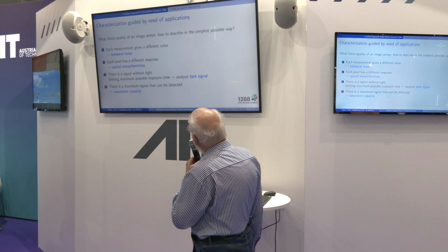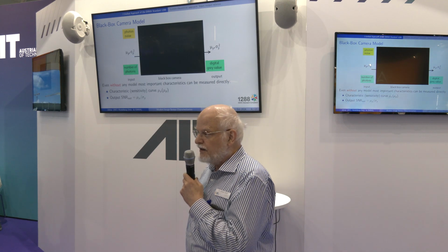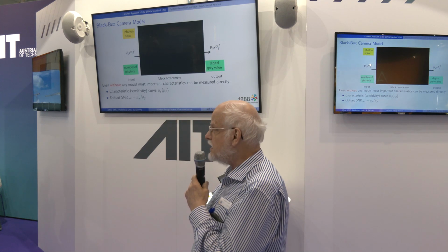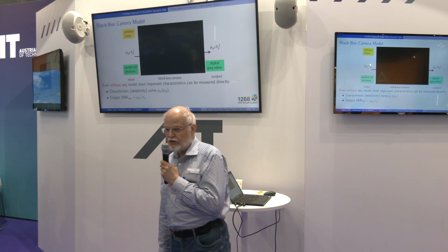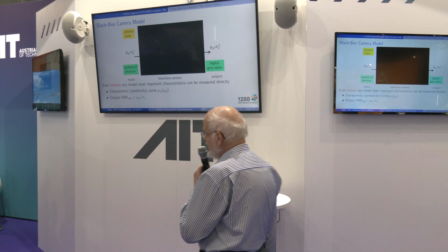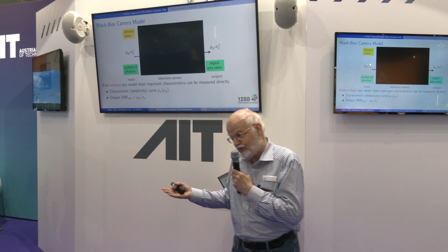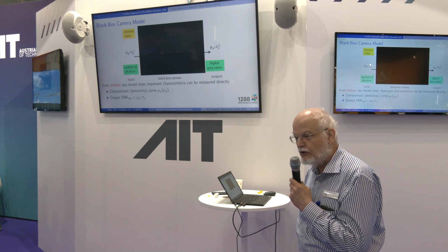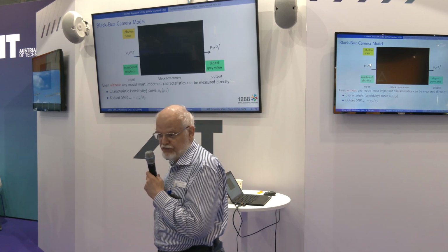And how can we now get them? The power of the system theoretic approach is that we do not know anything about what is in the camera. It's simply a completely black box. So we do simply an input-output relation. The input is the photons which hit the pixels during the exposure time. This gives us a mean number of photons. And this signal is already noisy because that is what is coming from quantum mechanics, that the variance is basically equal to the mean number of photons you have. No camera manufacturer can avoid this noise.